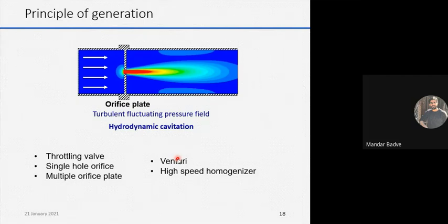Because obviously the pressure is very low in the tap, the cavitation won't take place there. But imagine the same thing happening at higher pressures in a controlled condition. The same thing happens, but you reduce the pressure so much that it reaches the vapor pressure, and then you actually get a cavitating condition, right? So this is basically how cavitation takes place, like I said, in the case of orifice or venturi devices.